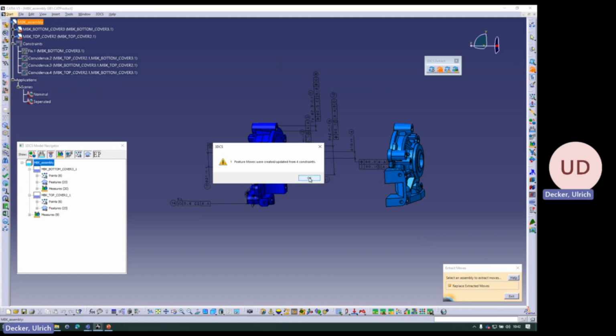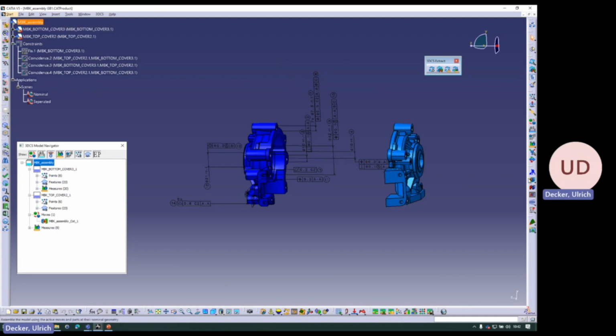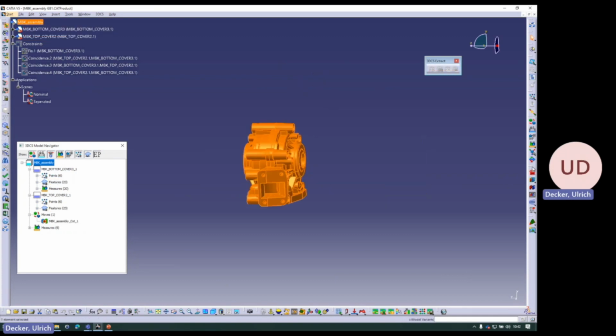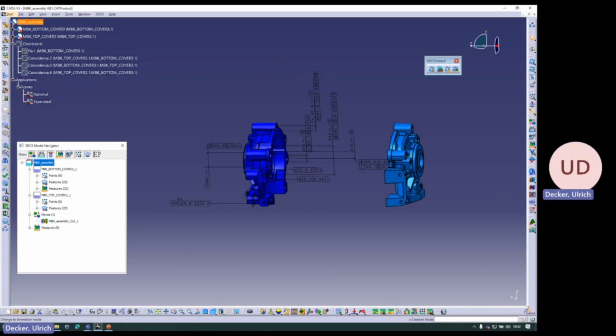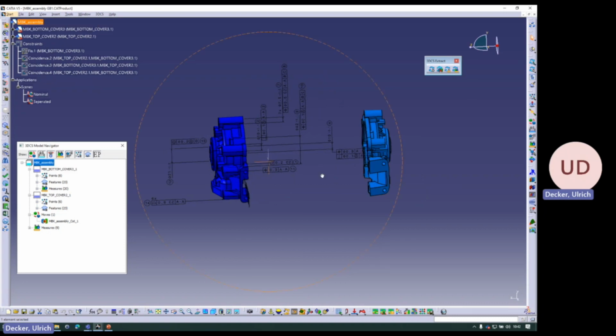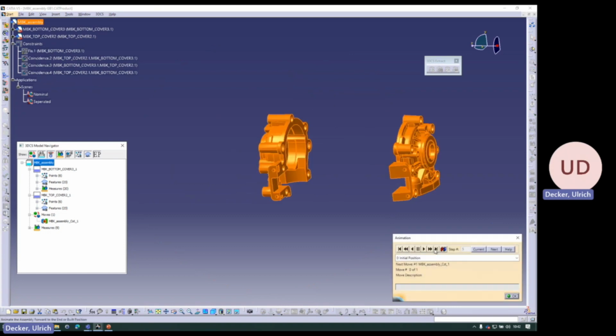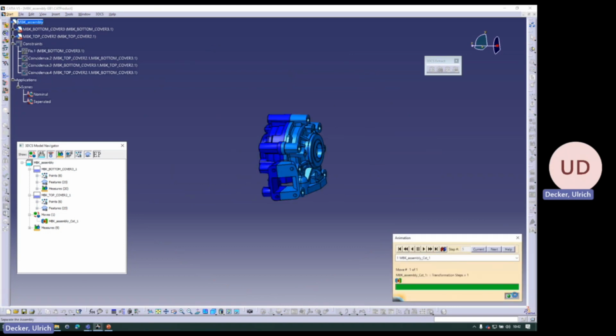So just taking this workbench, let's import the constraints and joints into the simulation. And this is what I did here, and you see the tree get enriched. Now if I hit nominal build, you see the parts are moving properly together. And this is also why we have that explosion situation, because of seeing the parts working step by step together.